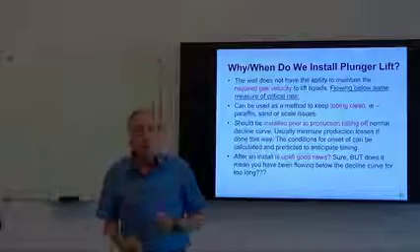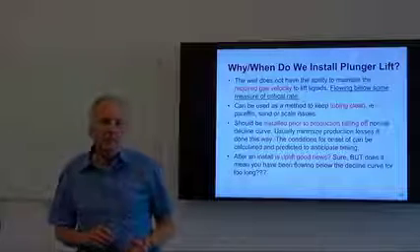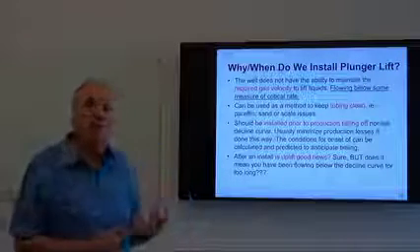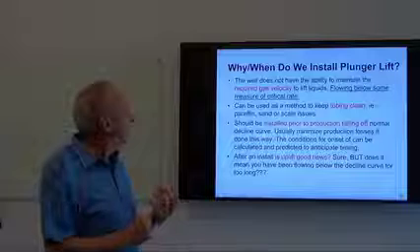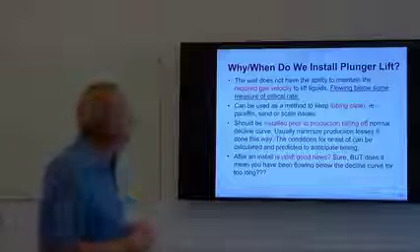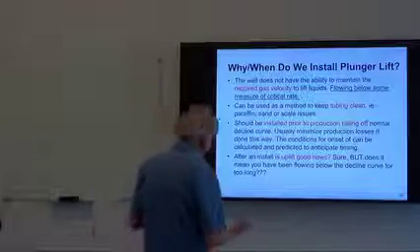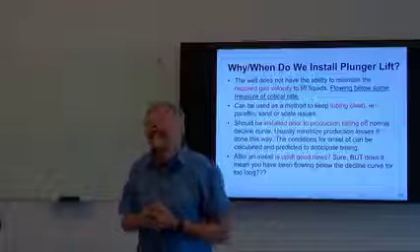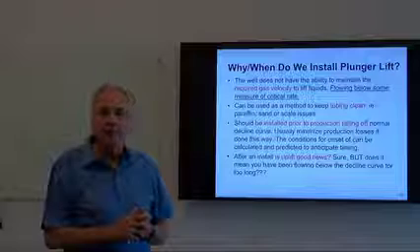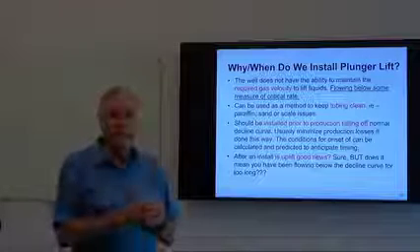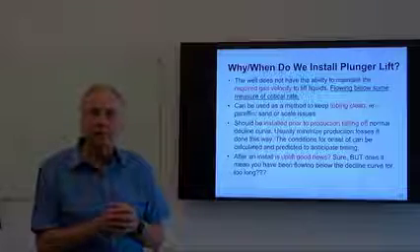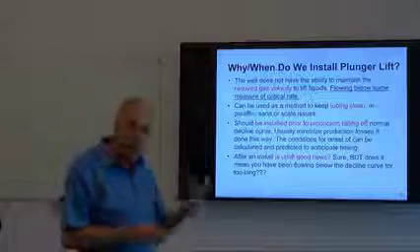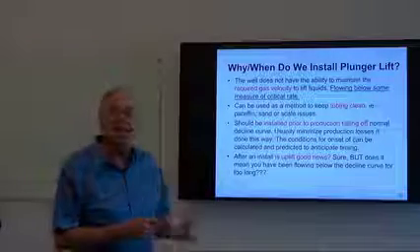Plungers are also very good mechanical cleaning devices. They can be used to keep the tubing clean. We are seeing this particularly in liquids-rich plays. Paraffin is very often a problem. It will accumulate and start to block off the flow path through the tubing. A plunger can stay ahead of that.